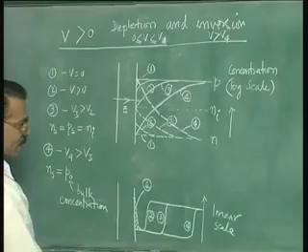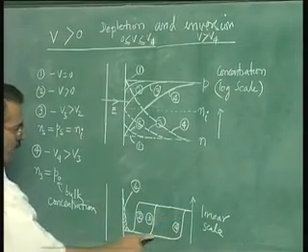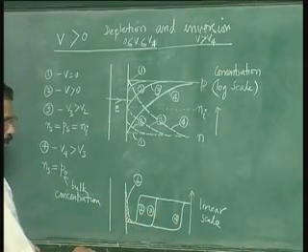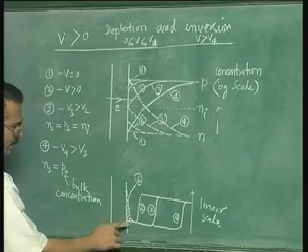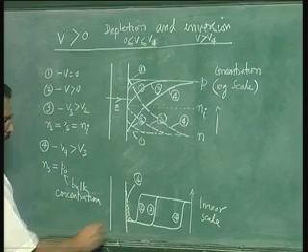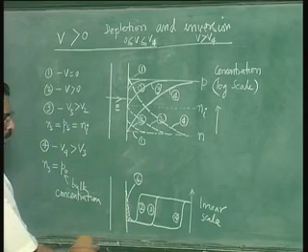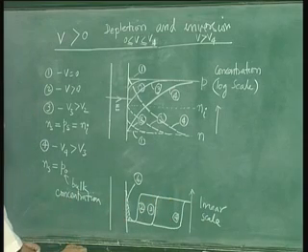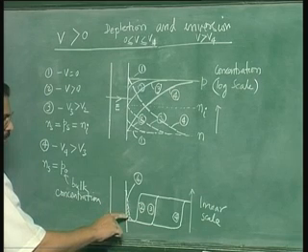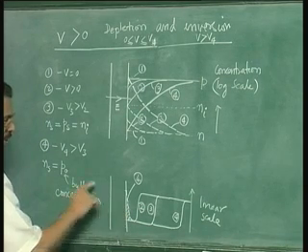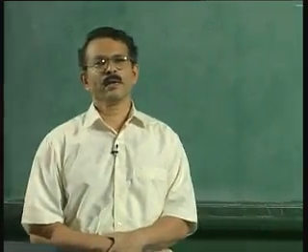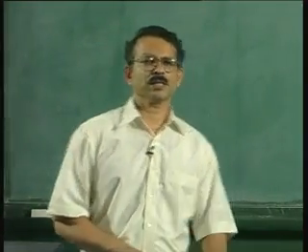Now for the threshold condition, the hole concentration is shown here, and the electron concentration also has been shown. It turns out that this electron concentration, that is the area under the electron distribution, is really small compared to the charge because of depletion of holes. So we can neglect this charge under threshold voltage conditions. That being the case, we can draw the charge and electric field conditions as follows.